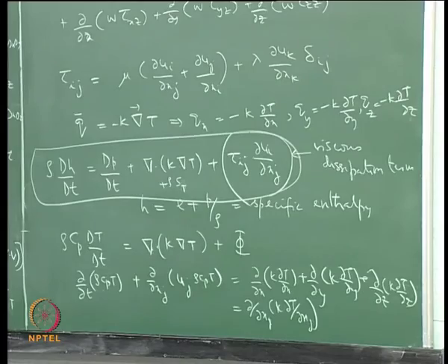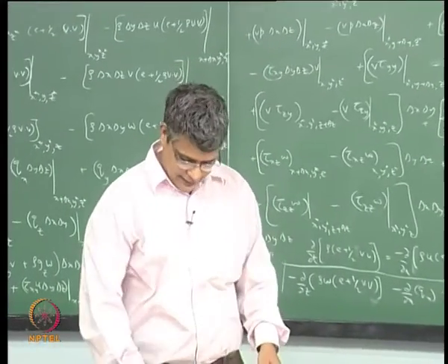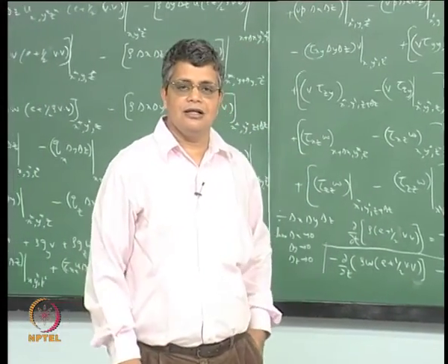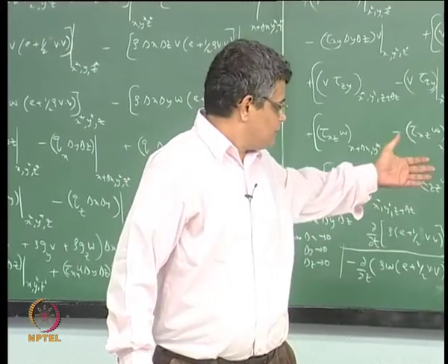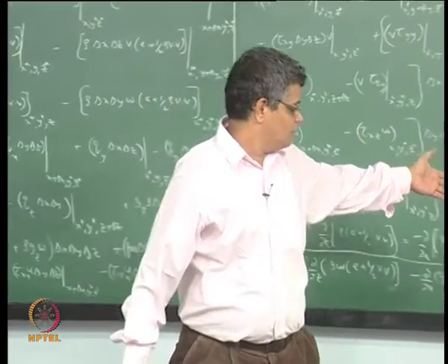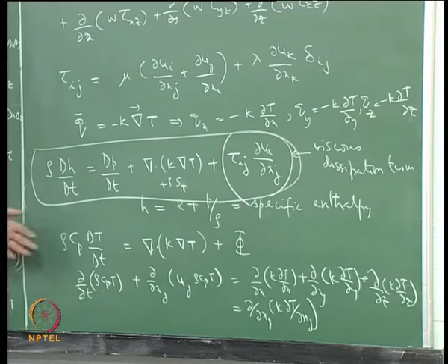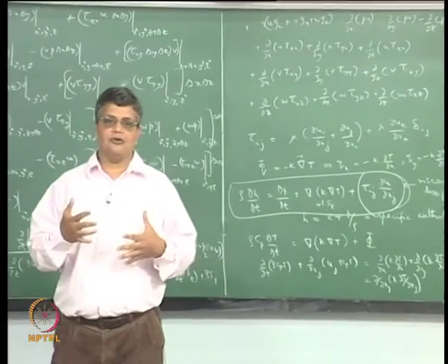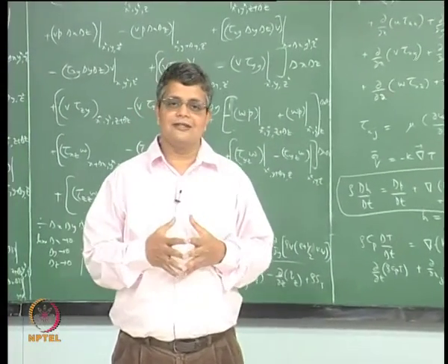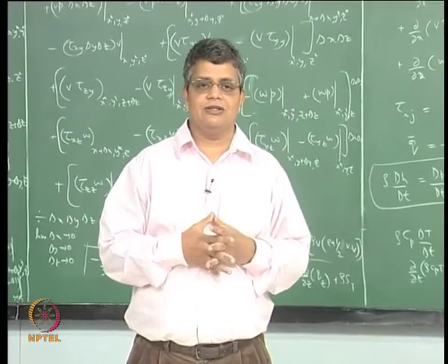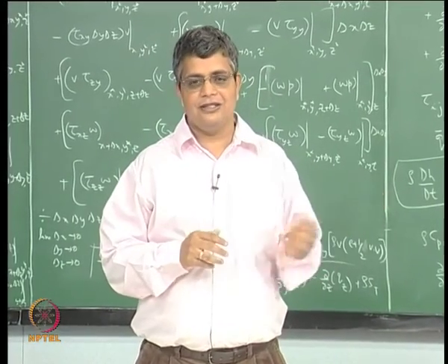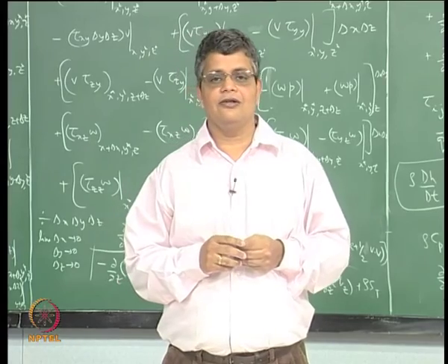So when we want to deal with the energy equation, when we want to deal with non-isothermal flows, then we have to solve an equation of this form, which is a standard scalar transport equation form, which introduces one extra variable and also brings in one extra equation. Therefore, we are not disturbing the overall balance of equations versus variables. So in this way we can take care of all non-isothermal flows.